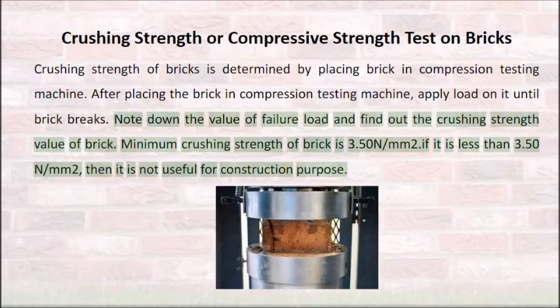Minimum crushing strength of brick is 3.50 N/mm2. If it is less than 3.50 N/mm2, then it is not useful for construction purpose.